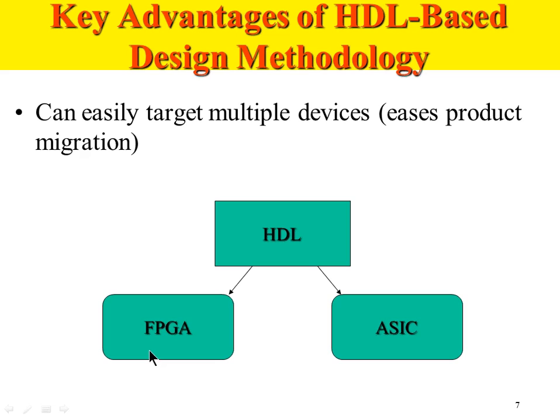Even with FPGAs, maybe today you are developing using a Xilinx FPGA. Tomorrow you are trying to develop the same design using an Intel FPGA or a Lattice Semiconductor FPGA. The same concept applies. The same Verilog code can be taken and implemented on a different target device later on. I don't have to change my Verilog, assuming the Verilog that I have developed is technology independent.